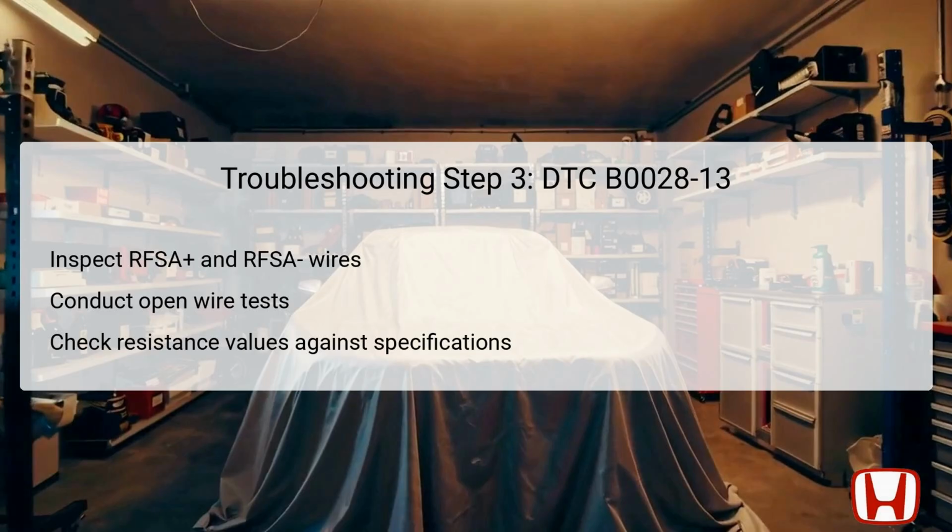If the readings show higher resistance or indicate an open circuit, this signals a fault within the wiring harness that necessitates repair or replacement. Such inspections are vital to confirm that all components can communicate properly with the SRS unit, ensuring that the airbag will deploy when required.